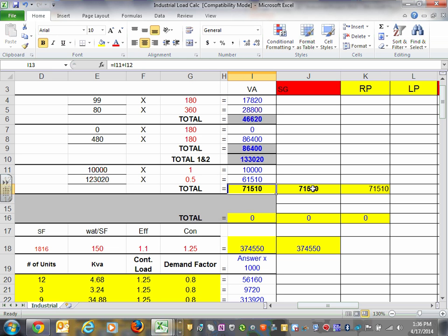So then, what I did in this sheet, and you don't have to do that, but that's one way of doing it, is we have columns here. The first column is sizing the switchgear. I need to pull all this information into one sheet and size my switchgear. So I pulled this number in here, so it can be counted under that column to size my switchgear for me. I want to walk you down here too.